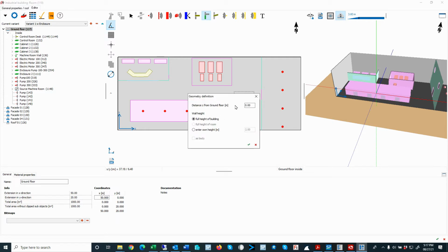Then here we can define that the enclosure starts at whatever elevation, in this case on the ground level. I can go to a height of maybe 2.5 meters, and I create it as a body. A body basically means it defines the walls and a ceiling, so it automatically puts an entire enclosure over whatever is included inside that area.